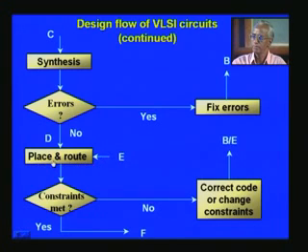So what place and route is: in synthesis you will get a gate level netlist. For example, an FPGA will be using what are called lookup tables, MUXes, and the like. All basic primitives pertaining to a particular FPGA, or a group of FPGAs, will have similar gates or MUXes and so on. So the synthesis tool will give the netlist in an EDF file, and that will be the input for place and route on the particular platform.